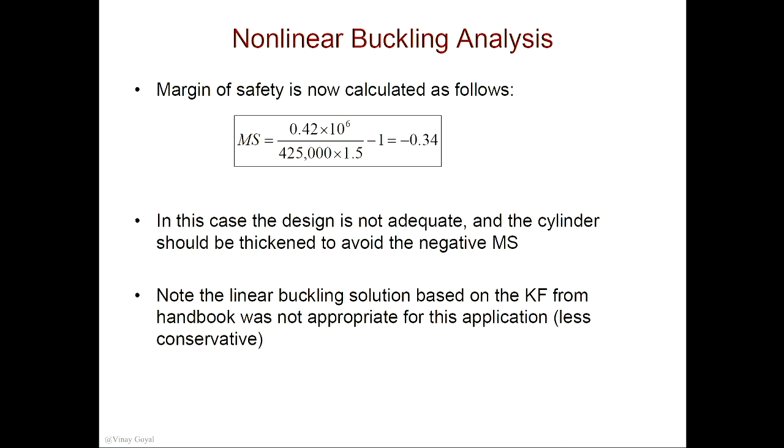And you can see here that this is probably more realistic if that was our case, if we had an imperfection that had those amplitudes. And so not always is a handbook a good choice. Sometimes you may want to do this kind of analysis to study the sensitivity of the structure you're working on to buckling, to make sure it's not buckling much earlier than what you thought. And so, all right. Do you guys understand what we've just done? Yes? So let me summarize it really quick.